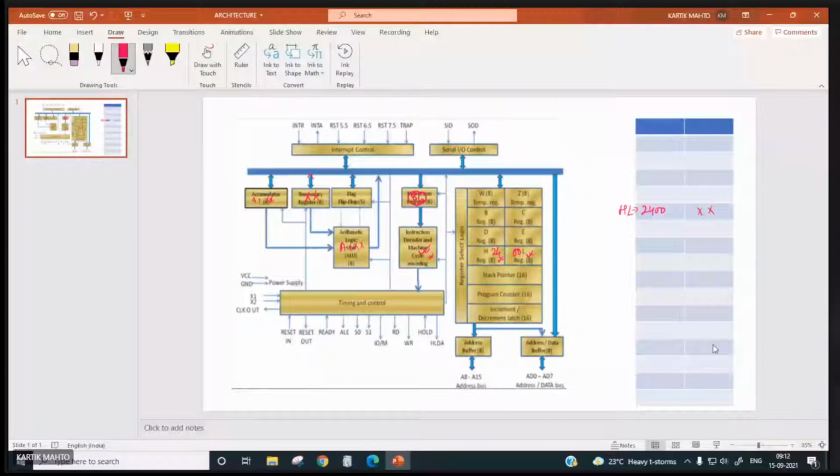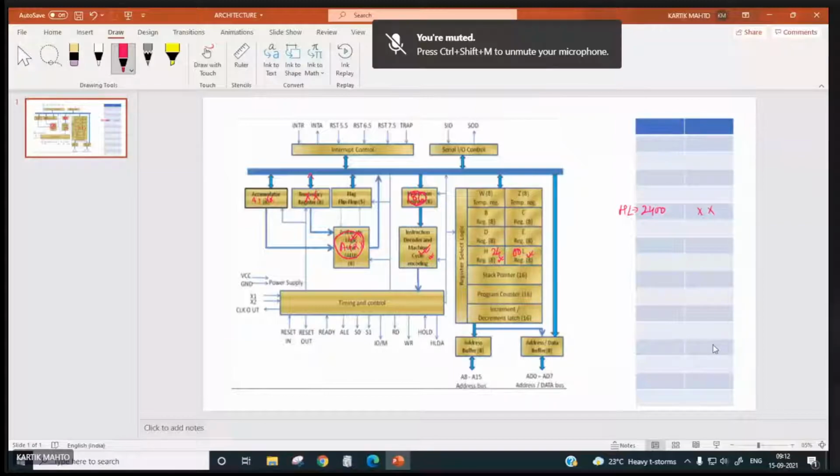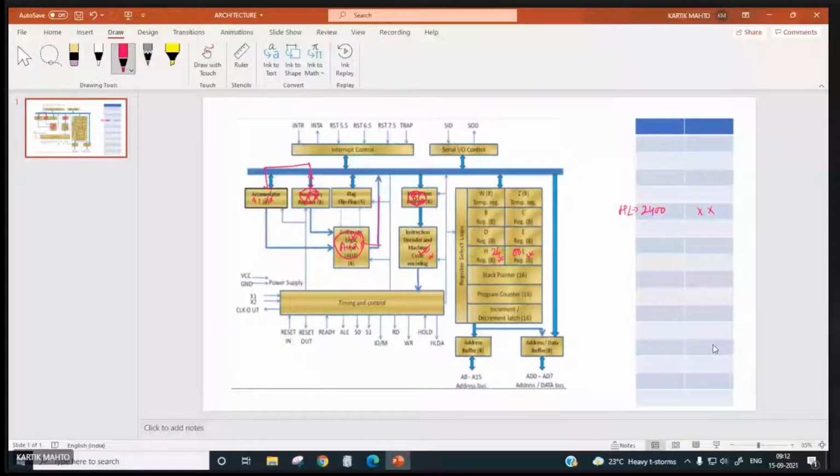It will be copied to the temporary register, then accumulator plus temporary will be done, then it will be stored back in the accumulator. During this process it goes to temporary, and then from temporary to the accumulator. This is the process. And why is it going through temporary? In order to reduce the number of micro instructions. Anyway, up to this we discussed.